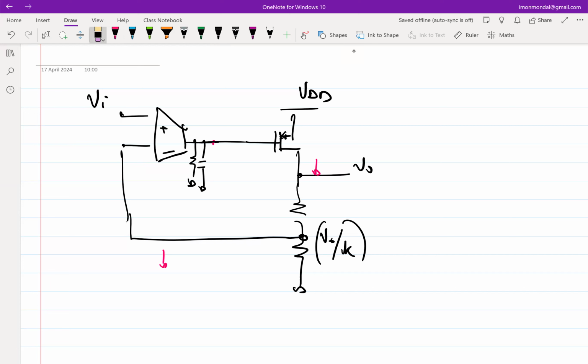So now, this is a differential amplifier. We know this is a differential amplifier and which is kind of symmetric. You can apply the input at either side of a differential amplifier. So if this is negative, this is not a negative feedback. All we have to do is to flip the places where we apply the inputs, right? So what I'll do, I'll simply flip this. This becomes plus, this becomes minus, and now your loop is in negative feedback. Okay, fine. So that is one.